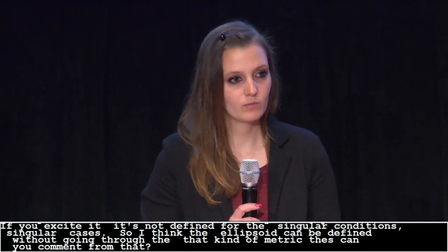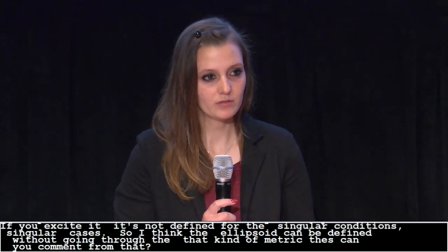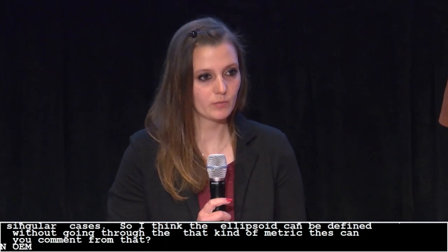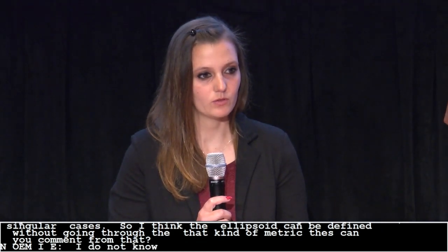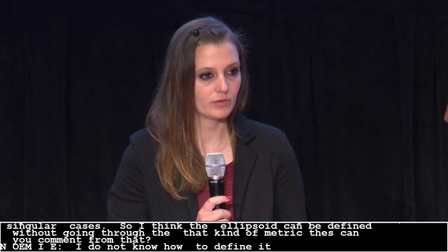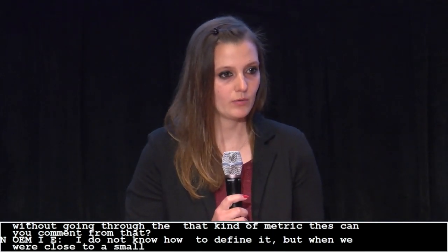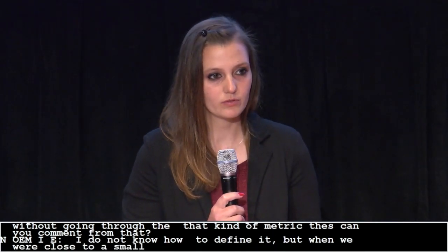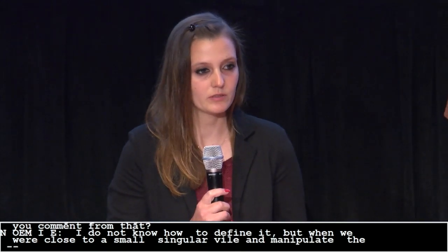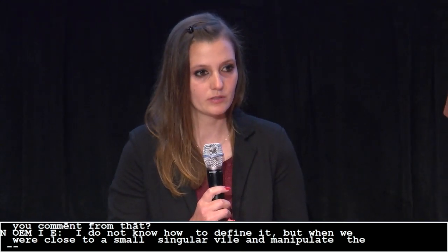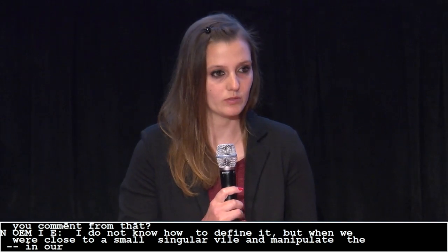I don't really know another way to define it, but when we are close to singularity, we add a small singular value, and we can then compute the manipulability ellipsoid. And in all our controllers, we implemented singularity avoidance, so we don't have any problem to compute it.